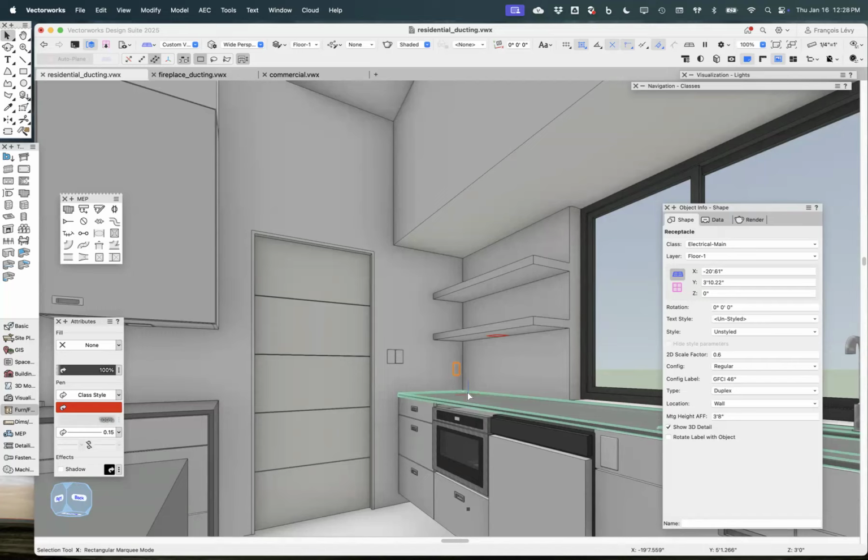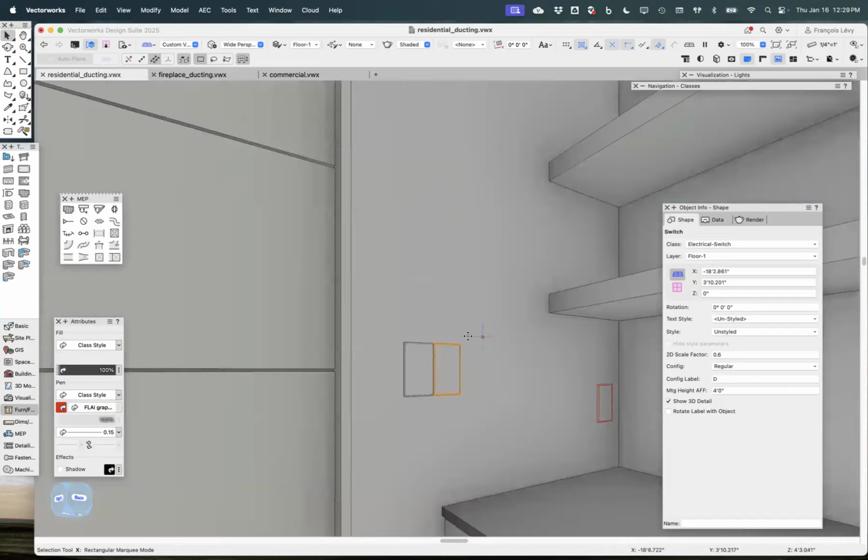And as a matter of course, I don't put them right next to the jamb because I know there's one or two studs at that doorway. And so sometimes I'll stack them one on top of the other, right? That's kind of a design move, to just stack two switches on top of each other. Or you can get those more expensive switches where there might be two or even three switches in a single box, if you need to.